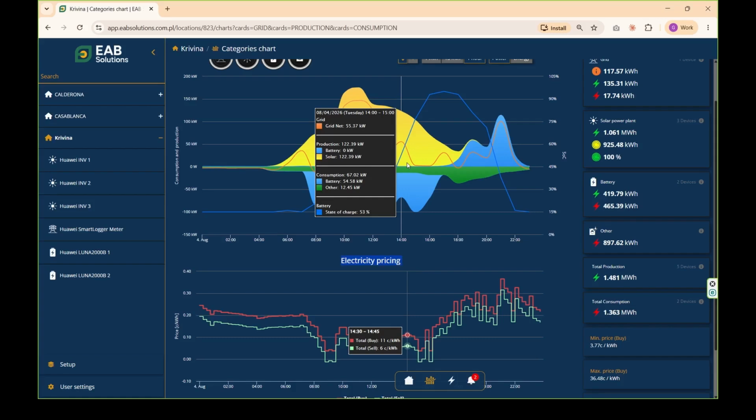But, as I say, the PV production would keep being consumed, and it wouldn't be fed to the grid, because that's not allowed. In many cases, feeding the grid is prohibited, but that's no problem at all. We don't need the battery. We don't need our EMS either, because we have safeguards. If the EMS fails, the data logger of the PV inverters itself takes care of guaranteeing zero export.